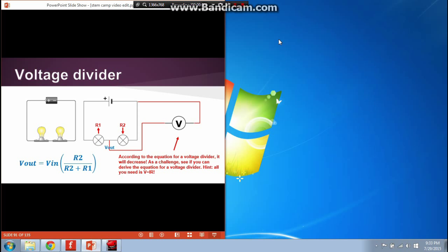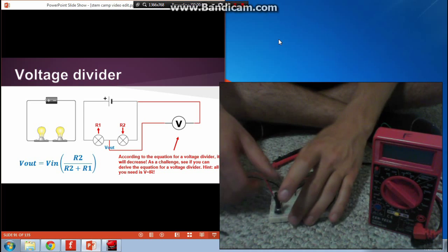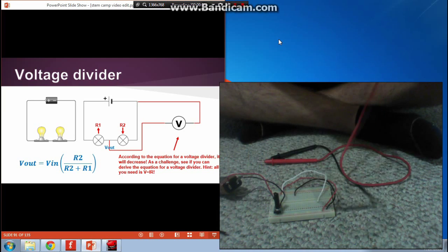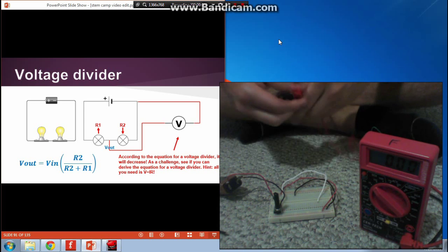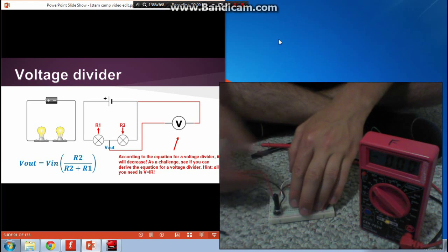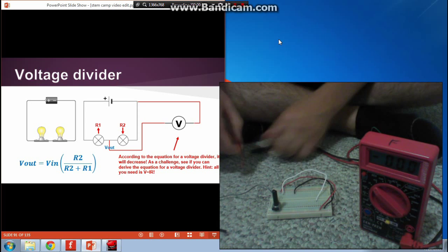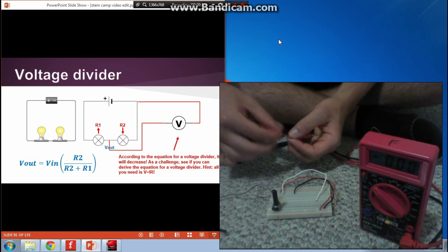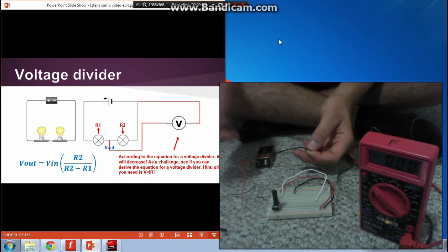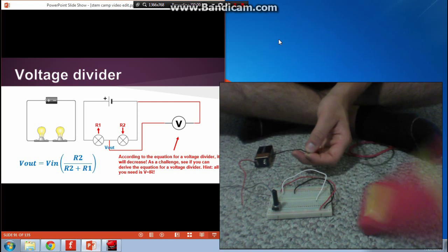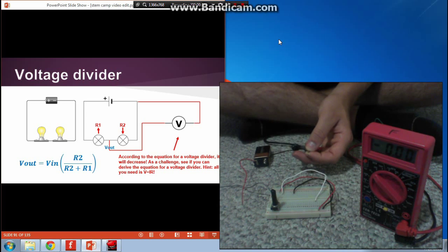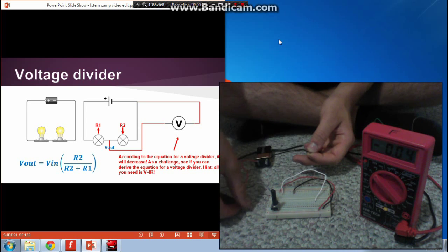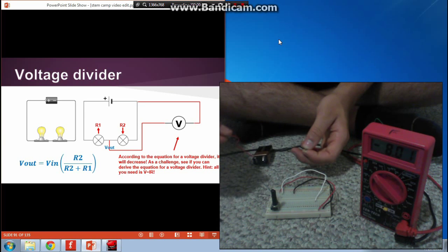All right, let's just give this a shot real quick. I'm not sure what all you can see, but I want to show you guys how to use a voltmeter real quick in case you don't already know how, and even if you do, it's never too late to refresh. So first, I'm just going to connect. Really, this looks like a series connection, but it is in fact not in series, because the voltmeter has what's called a very, very high impedance.